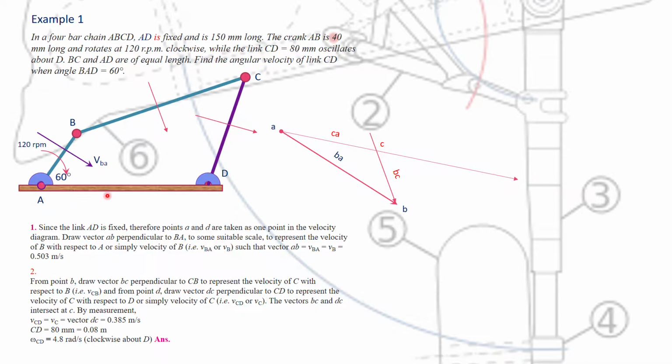So first thing you have to draw a space diagram. Once you have got your space diagram drawn, remember each of these members here, AB, BC, and CD, you must draw perpendicular lines like that. Make sure it is perfectly perpendicular, or 90 degrees. You have to use a protractor for this CD, BC, and AB. So you got this line, and this line.